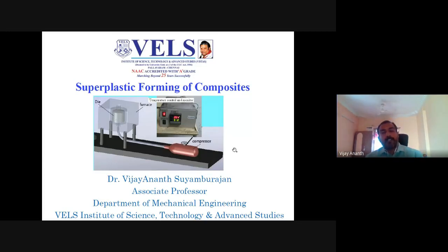Okay. Today we are going to discuss superplastic forming. It is one of the sheet metal forming processes. With the help of heat, we are making the components. Normally, at room temperature, metals have very little ductility. Aluminum has a ductility of only nearly 10 to 12%.